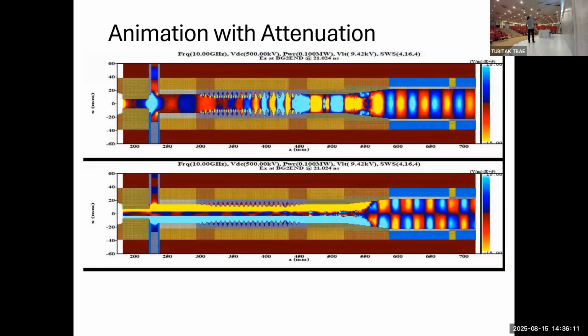If you don't couple all the power, you have reflection back to your source, the seed signal. And for 100 or 250 kilowatts, a circulator is really expensive even for a couple of kilowatts, and if you go to hundreds of kilowatts, that's a really expensive part that you don't want to invest in. So you want minimum reflection that is not affecting your source.